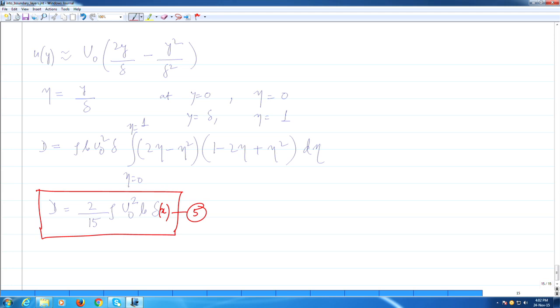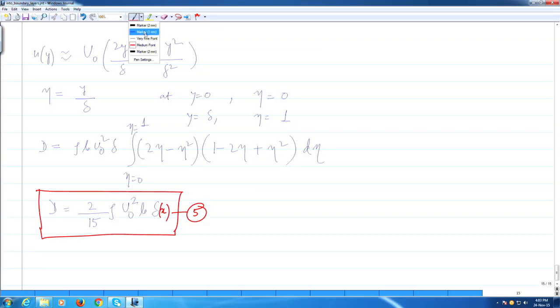So, let us call this that. Now, this is from our expression here. Now, Kármán of course, is we are integrating the shear along the plate. Now, in our case, of course, the drag is essentially the shear stress which the fluid is exerting on the plate by means of its viscosity, right. So, let us say the shear stress is tau w, okay, and we multiply that by the area to give us the shear force. Okay. So, how do we do that? So, therefore, we write the drag.